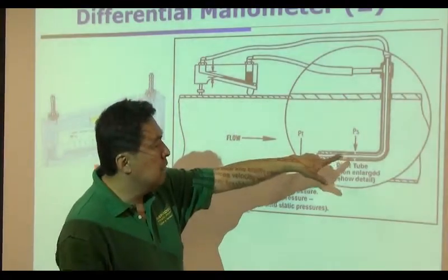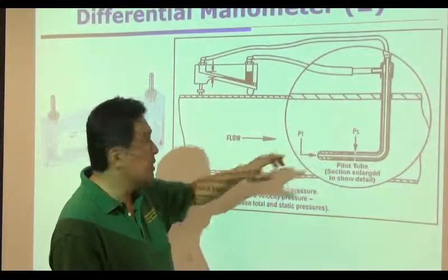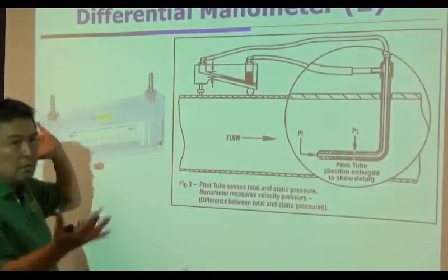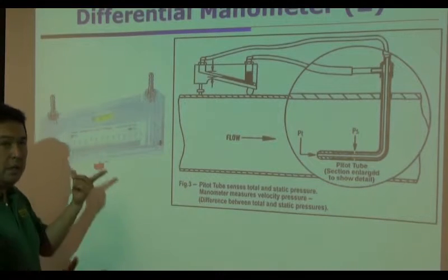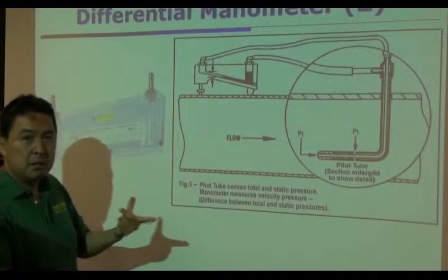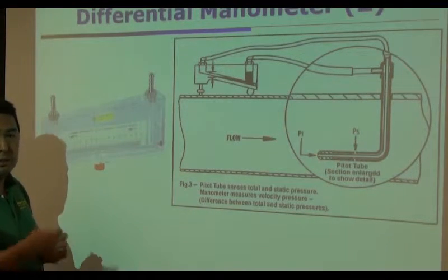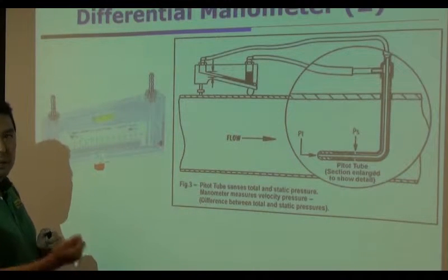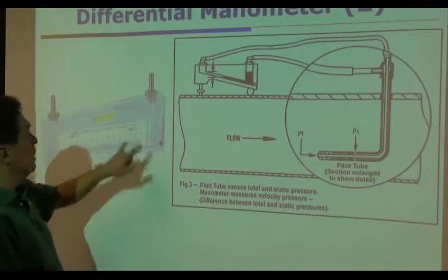So when you walk into the wind tunnel, and you ask somebody how fast this wind tunnel can go, the typical answer is, well, 5 inches of water. What do you mean by that? Well, that's how much dynamic pressure head you can produce by turning on this fan to the maximum speed, which is converted into how many inches of water rise up in this manometer.